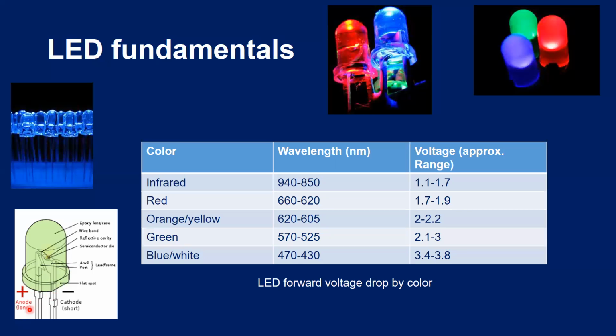For example, you see here in the schematic, this is a light emitting diode. One lead is termed as anode, the second lead is termed as cathode. Anode is usually the long lead and cathode is shorter. All right, and here the internal annotations indicate the different parts of this device.